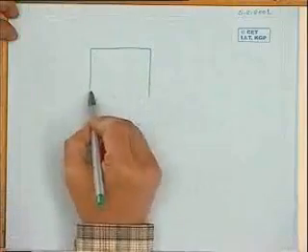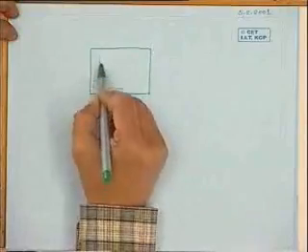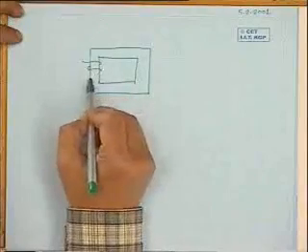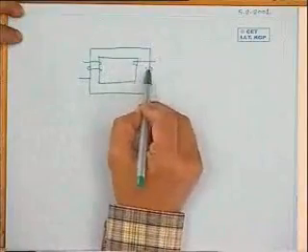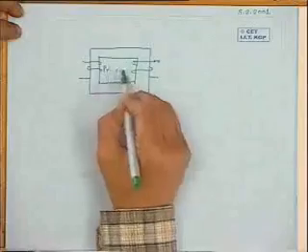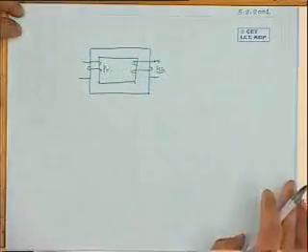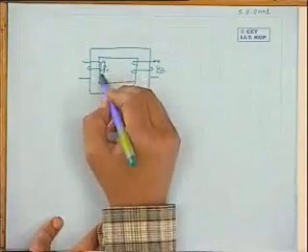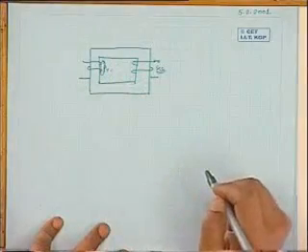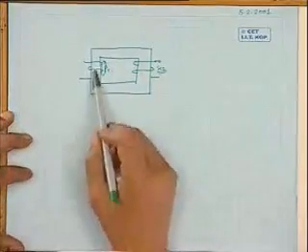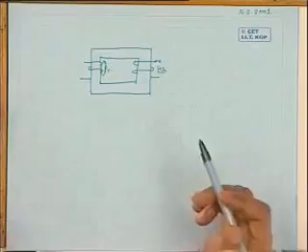While drawing so far a transformer, I was drawing like this. Suppose this is the transformer. I was drawing like this. This is the primary winding in one limb and secondary winding on the other limb. Is not? This is how I am drawing. This is the primary, this is the secondary. Now, the leakage reactance, as I told you, is caused by the leakage flux. The flux which only links a particular coil is not a common mutual flux.